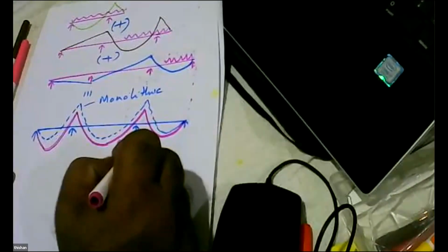What are we going to call the lower one? We call it as-built. It's not monolithic. That's how it is built. Then you will ask, okay, so why bother? Just use the as-built. Only thing is, you have to look at the construction sequence and generate a bending moment diagram which is relevant to the construction sequence.